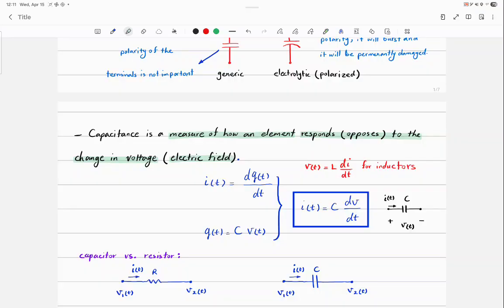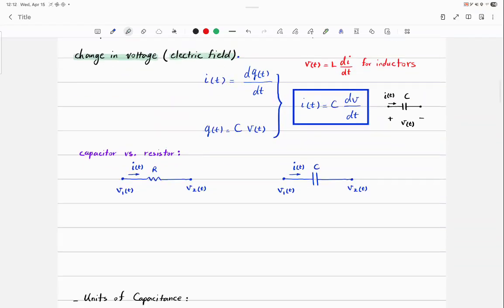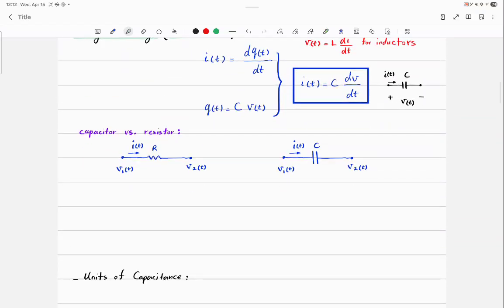Okay? Let's talk in terms of formulas. Do you remember what was the formula for governing the voltage-current relationship of an inductor? V equal to L di over dt, right? Now, can you tell me what's the dual equation? Instead of V, write I. What should we write instead of L? C, because the inductors change to capacitor. And instead of di over dt, we write dv over dt. You get the equation for capacitor, okay? C dv over dt. Let's compare capacitor and inductors.